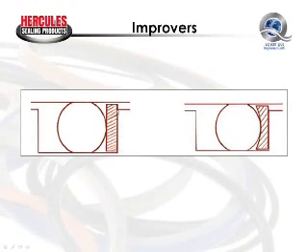This backup ring is a flat-sided backup ring. This backup ring is a contoured backup ring made popular by Parker called a par back. The concept here is that as the O-ring is deformed against the sealing surface, it pushes the O-ring back away from the extrusion gap. This is mostly a matter of personal preference between the flat backup ring and the contoured backup ring. They both work satisfactorily. Depends on which one you have a preference for.